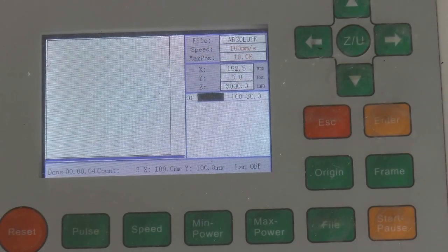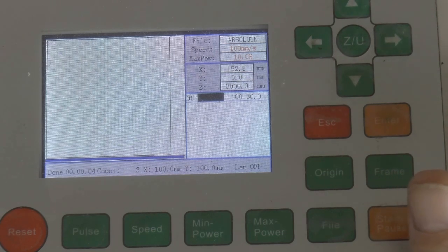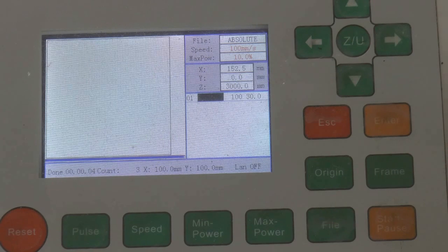But now we're going to try the absolute setting, and to make life easy here, because my memory is not quite what it used to be, I made the start coordinates for this program to be 100 by 100. So what I've done at the moment is to set this coordinate to some strange number like 150 in X and 0 in Y. The first thing I hope it's going to do when I press this button is go to position 100, 100 and draw a square 100, 100.